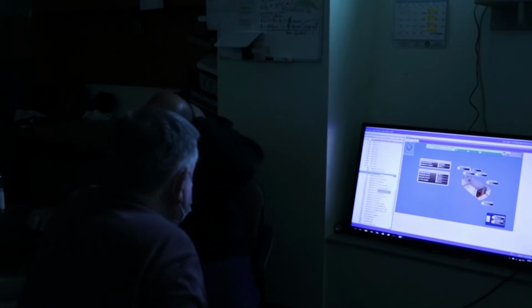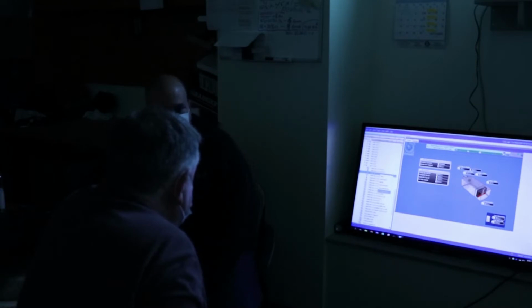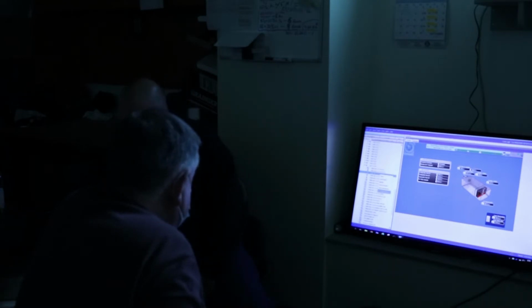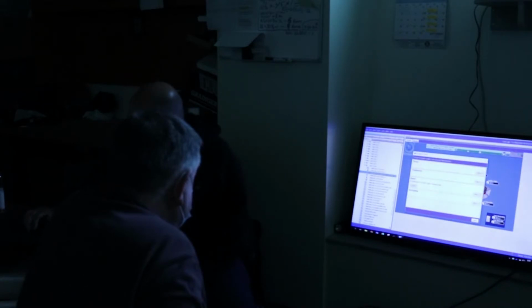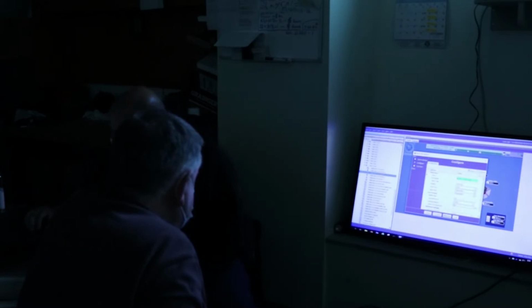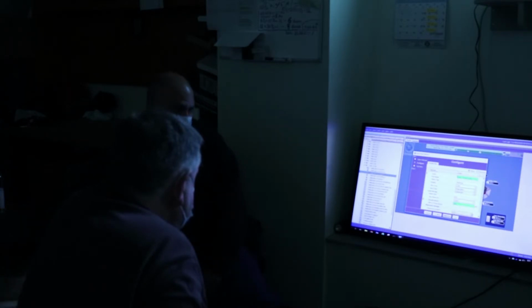So now we right click on it. We go to show extensions. Zone temperature, ZNT. So we go show extensions, and now we add a new trend. All right, we go next, and now here's the information. So we want to put in 1,800 seconds, and then we want to enable the repository so we keep the information.